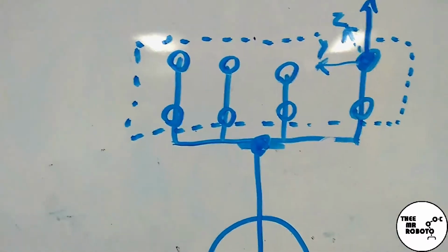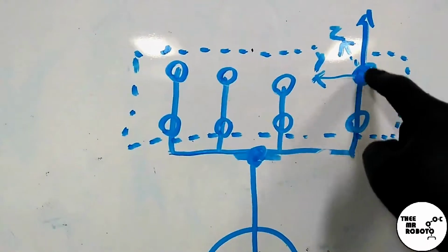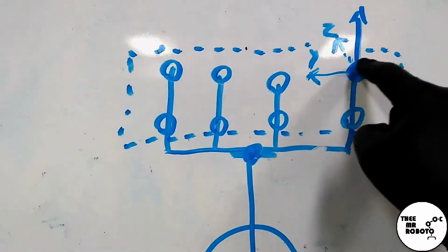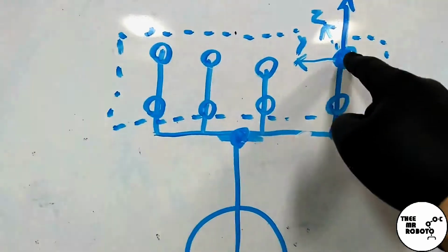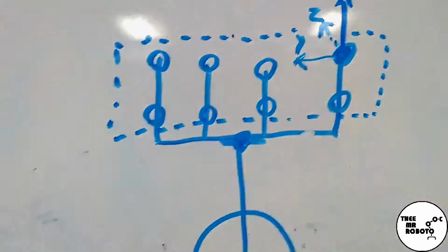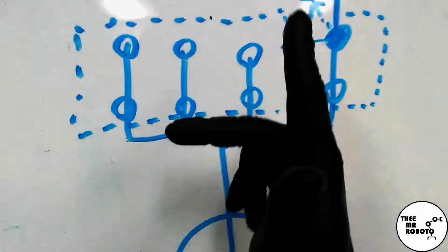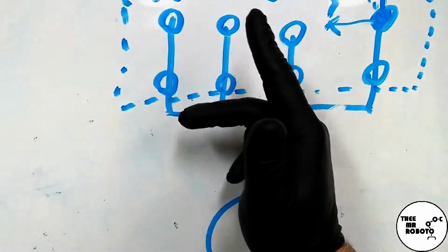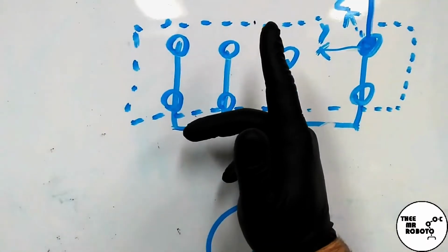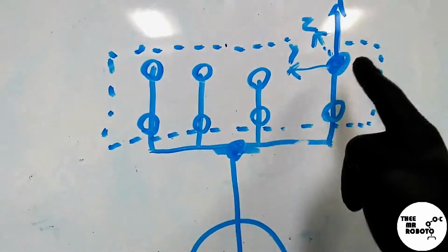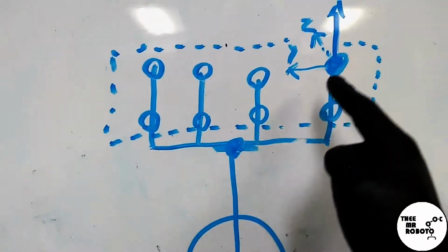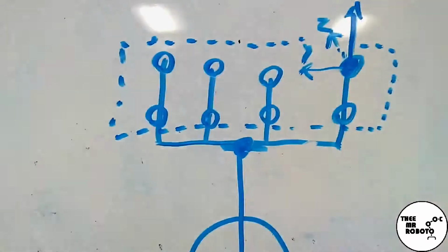But that doesn't really help us if we need to maintain the position of this critical geometry in the part. Maybe we want to rotate around that position, okay? So we take a coordinate system here at your flange, we create one over here that is an offset of this coordinate system, all right?